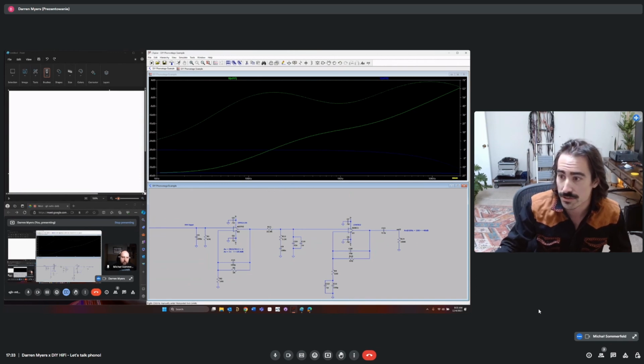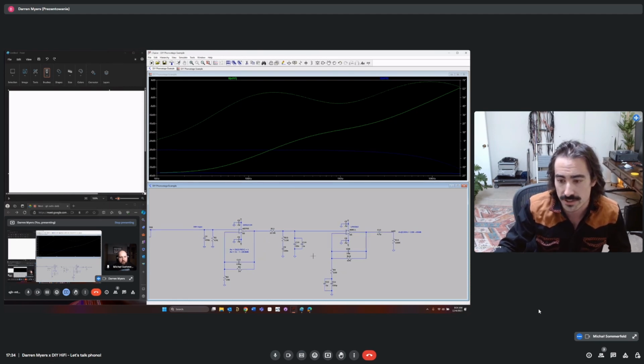And so we're actually losing 20 dB because we have to boost all the way up, where before we just had to boost this side from 1 kilohertz all the way up to our output amplitude. Here we have to take it from here all the way up. So we lose 20 dB of gain doing that. So you have to put 20 dB more into your output stage.